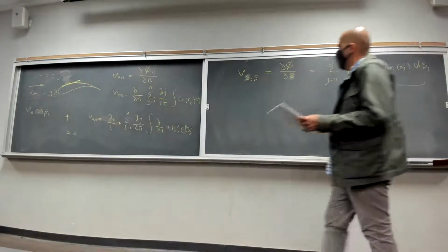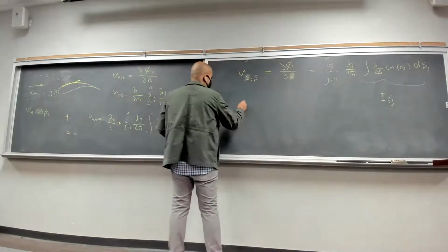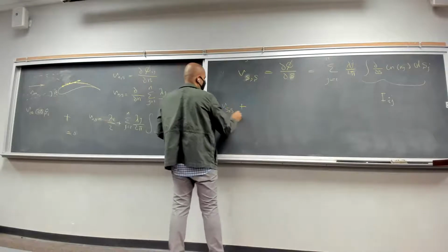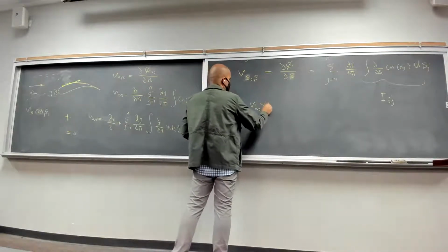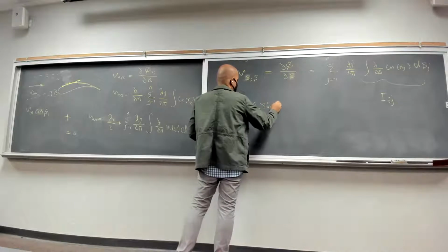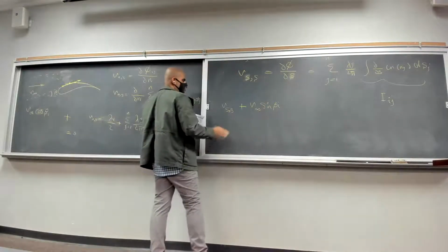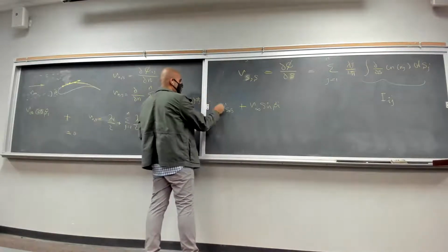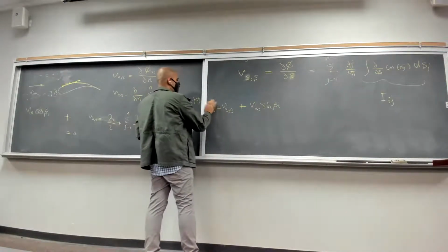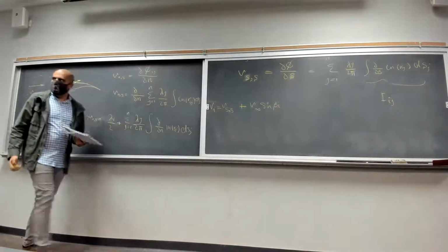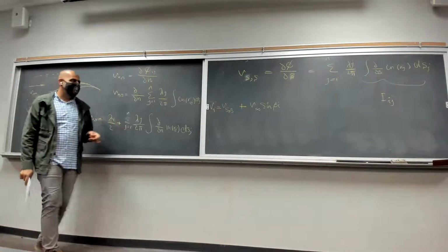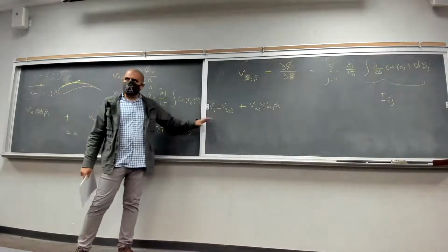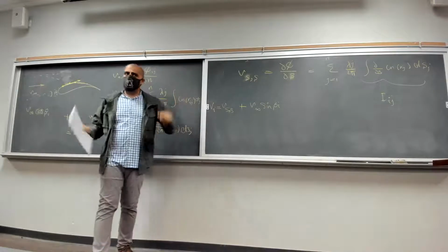And when you find this tangential velocity, just have to add this Vs and S to V infinity tangential component of free stream velocity, sine of beta I. That was the angle between the flight path and the panel to get the velocity of each panel. So eventually we have the velocity of one panel, okay? And you do the analysis for all the panels, you have the velocity for all panels.